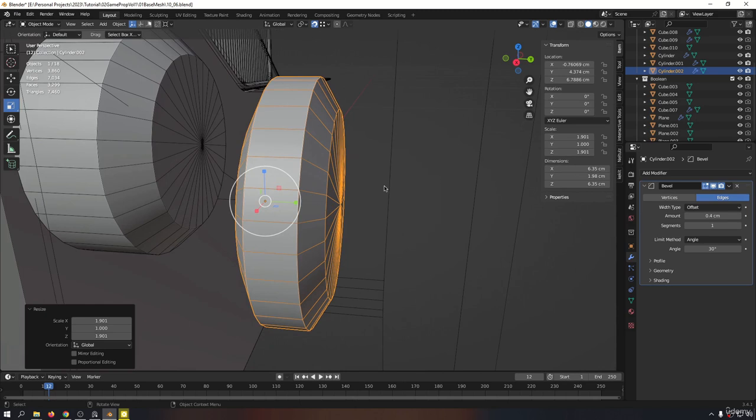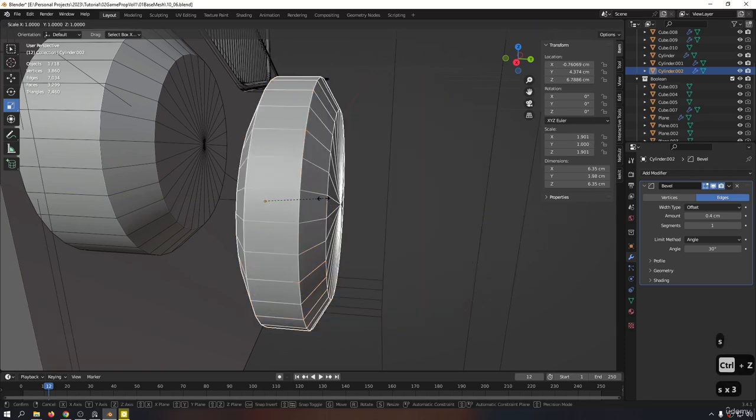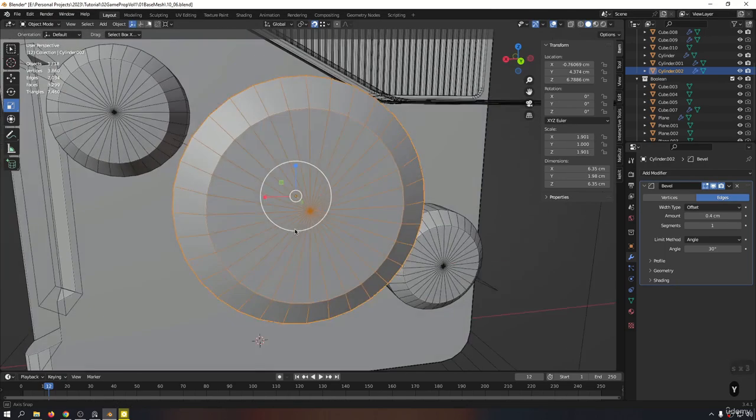So if you're going to include or exclude a certain vector from the scaling, you can hit that vector with Shift to exclude that. For example, in here we didn't want to scale that along Y, so I hit scale and then Shift and Y to exclude the Y from scaling.